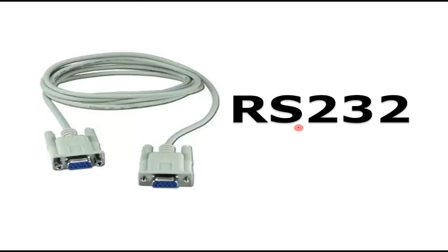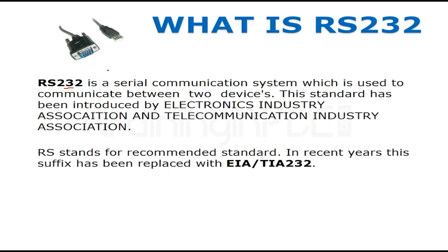In this session, let's see what is RS-232 and its pin configuration. RS-232 is a serial communication system which is used to communicate between two devices. This standard has been introduced by the Electronics Industry Association and Telecommunication Industry Association. RS stands for Recommended Standard. Earlier, RS-232 was called EIA or TIA 232.